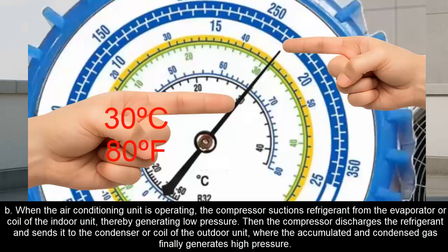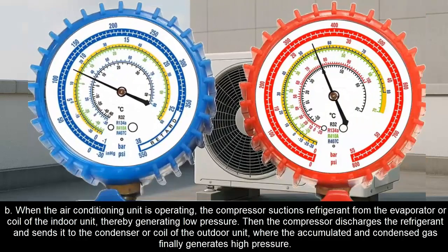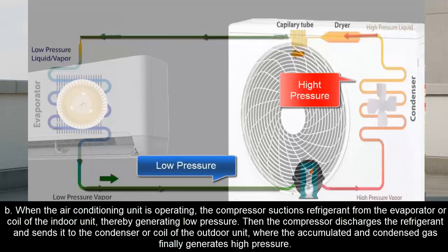B. When the air conditioning unit is operating, the compressor suctions refrigerant from the evaporator or coil of the indoor unit, thereby generating low pressure. Then the compressor discharges the refrigerant and sends it to the condenser or coil of the outdoor unit, where the accumulated and condensed gas finally generates high pressure.